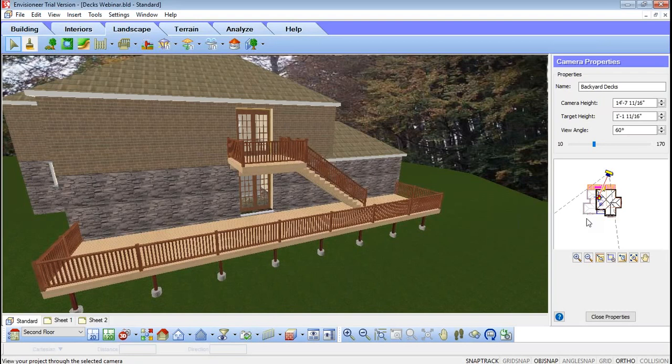If you wanted to adjust that, you could adjust the height of the pad itself, or you could create that pad as a floor instead and be able to elevate it up and down using the elevate command once you inserted your floor.